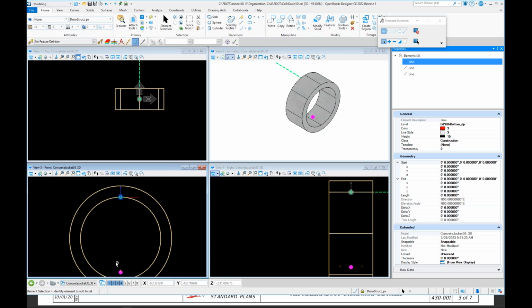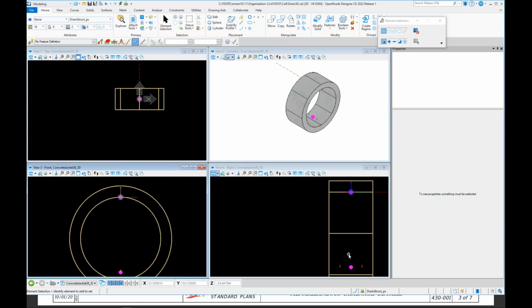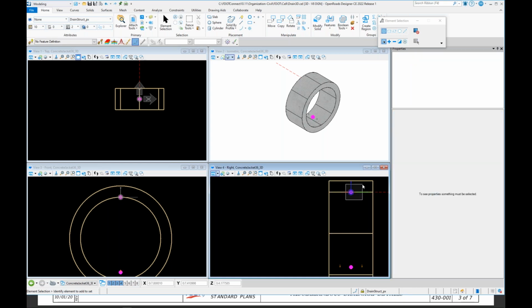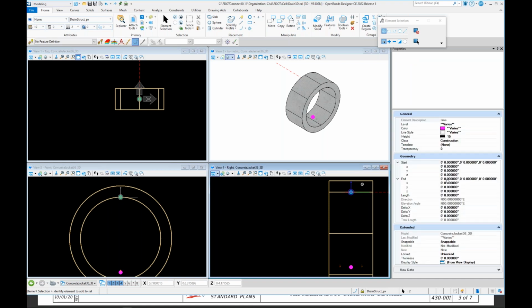You'll notice things on the other point down here are mostly 0 except for the Z offset. And the Z offset on this particular one is below the one above, so it will be a negative. The one up here needs to always be at 0, 0, 0, X, Y, Z.